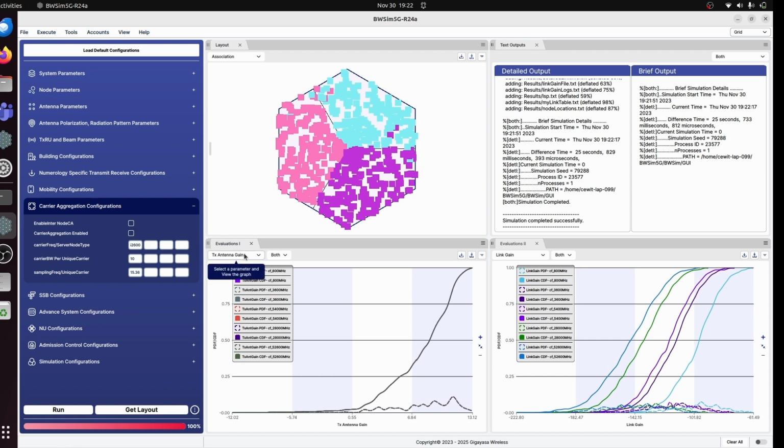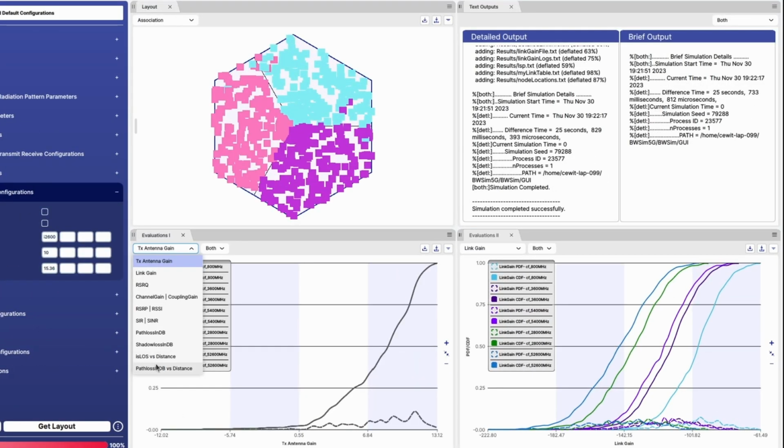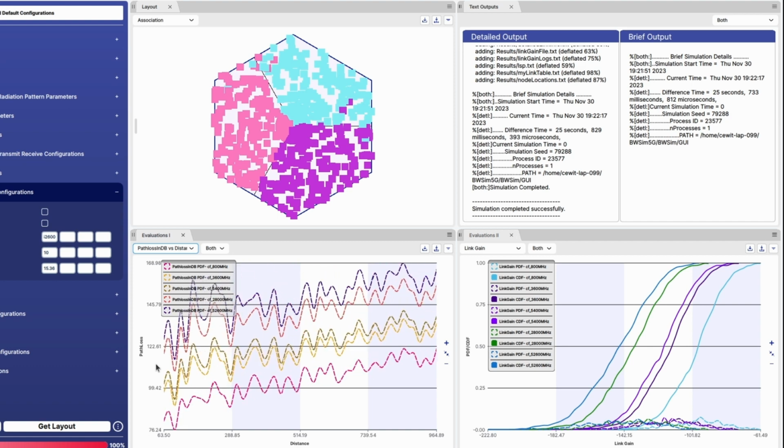Okay, now that we have conducted simulation for 5 different carrier frequencies, let us move to the parameter in question, which is path loss in dB versus distance of separation. We will separate the observation into two phases. The first phase is, you can notice that as the distance of separation between the transmitter and receiver increases, an increase in path loss can be found. This is because when you increase the distance between the transmitter and receiver, the presence of scatterers increases, thereby contributing to the increasing path loss.